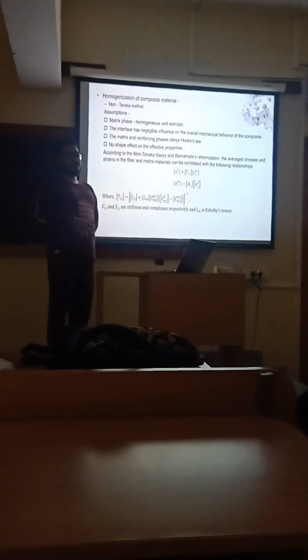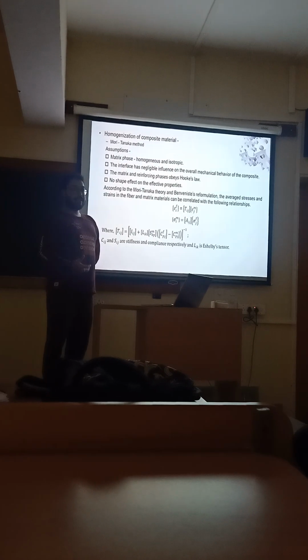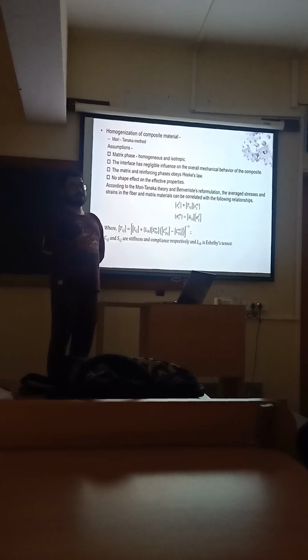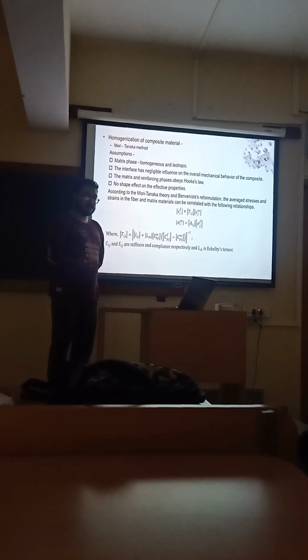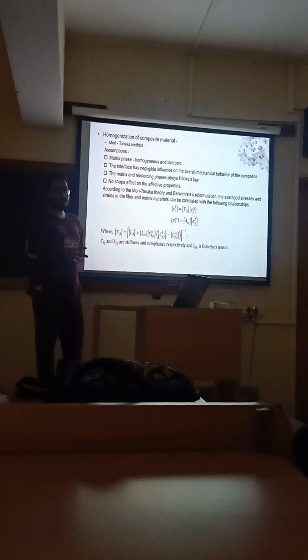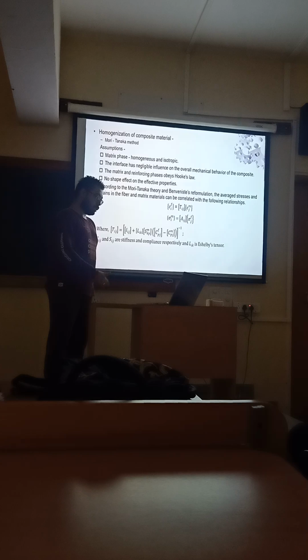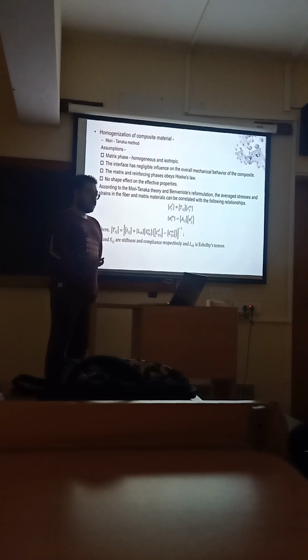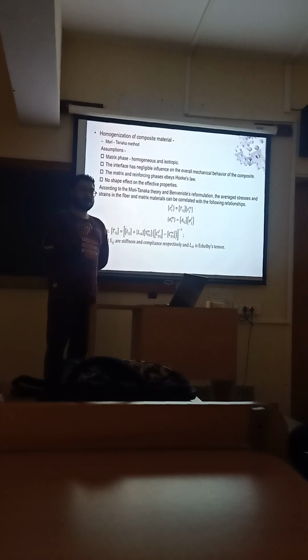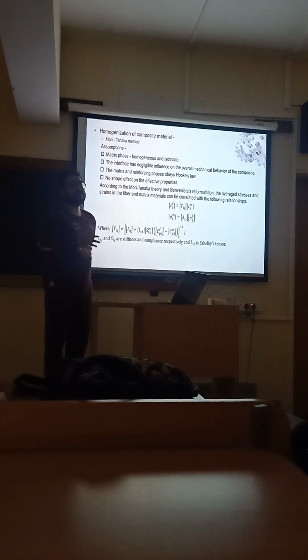Now, to analyze a composite material there are several ways. One of the ways, if you want to predict the nature, is finite element. It's a very accurate method to discretize the beam with different areas where you can assign properties. But I have not chosen that method because when I was doing this project, one thing I kept in mind was that my outcome should be such that people can easily implement it. It should not be very complex.